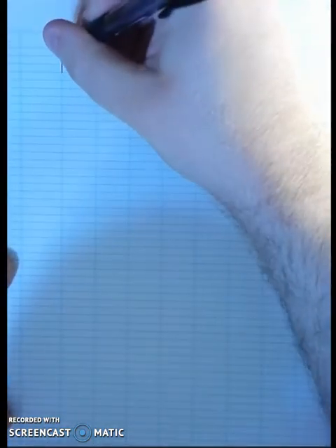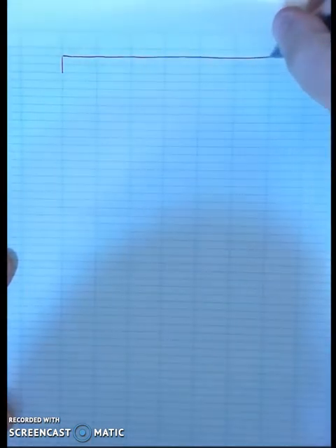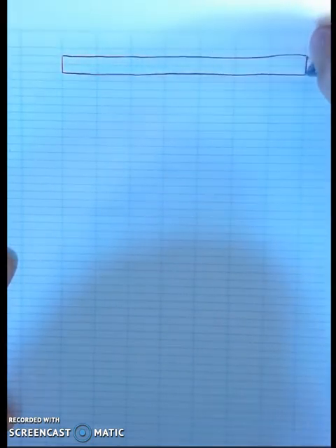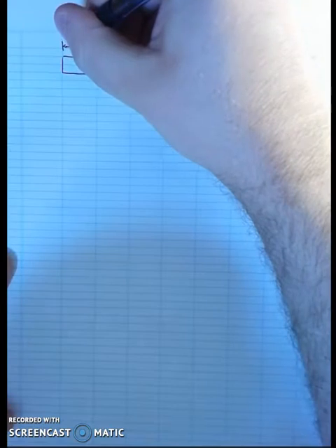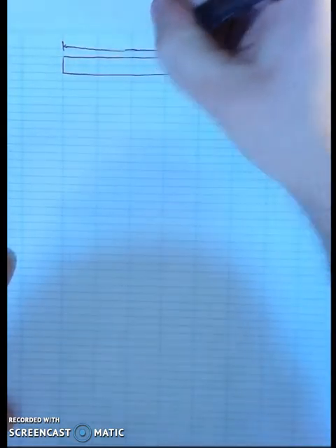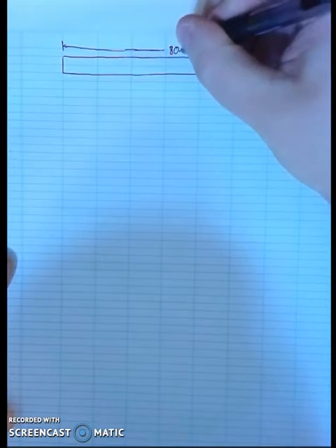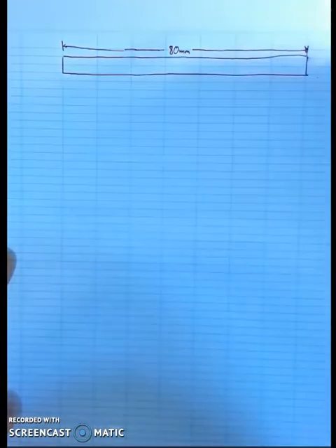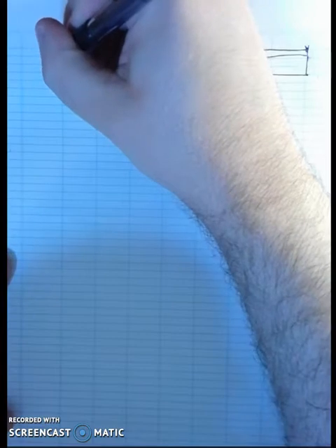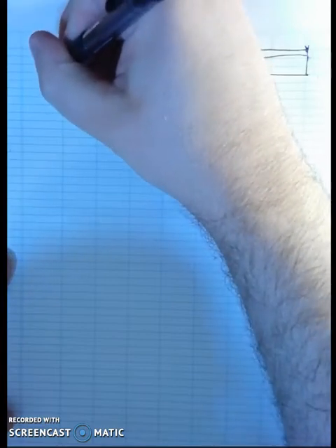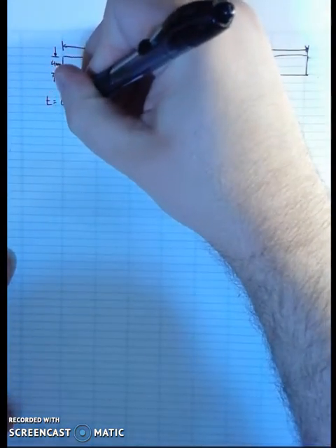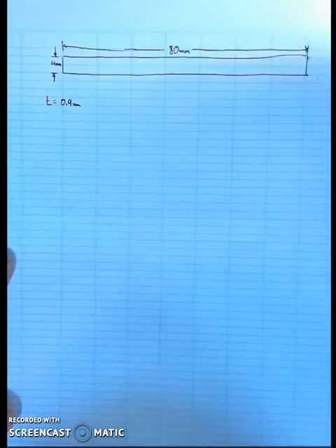So let's start out with the rectangular portion of the sample coupon, not necessarily drawn to scale, but just to give you a sense of the shape. Again, we said that these guys measure 80 millimeters from one fillet to another fillet, and their width is about 4 millimeters. And the thickness, that's the thickness into the page, is about 0.9 millimeters. Okay, so those are the critical dimensions.